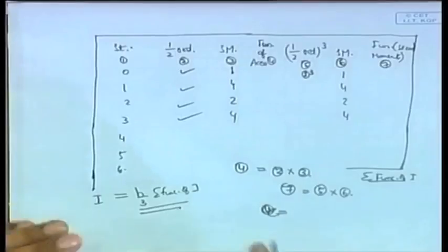Okay, you have to be able to find the I, and you have to be able to find the area, in case of volume or the displacement. So these three things, that's all: area, volume and moment of inertia. You should be able to calculate these, provided you are given the station and the half ordinate. Once you are given the station and the half ordinate, you should be able to calculate the I like this using this table. Once you have the I, note that this I goes into that equation. This final value is just one value of I for that whole tank about that central axis.